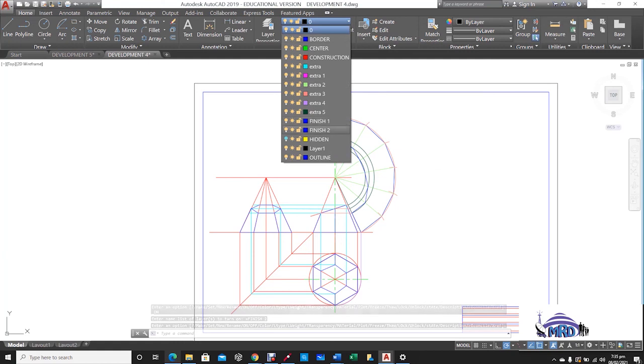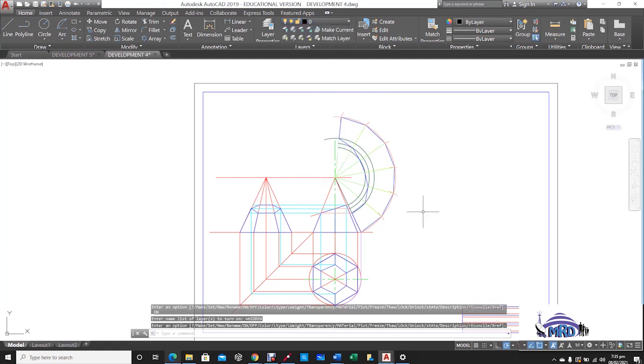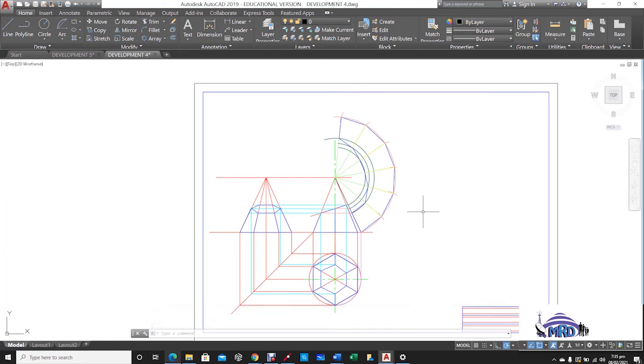So this is just an example for producing a pyramid, the development for a pyramid. I chose to do this one because it contains more details, and the first example that we looked at would have been relatively simple with the square pyramid, but I just wanted to show you another pyramid, another construction, so that you would see that the method remained the same.